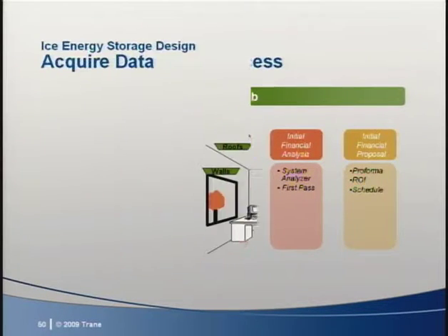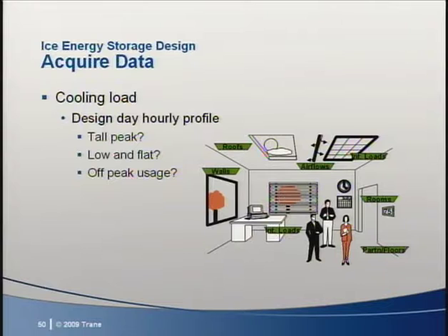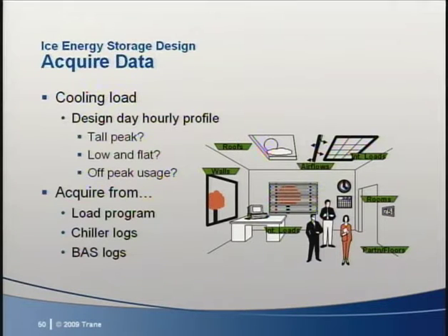It's important to understand not only the peak load value, but the shape of the facility load curve as well. Load curves for new buildings will obviously have to be acquired from a load analysis program. While existing buildings can be modeled that way as well, if chiller or BAS system logs are available, they can serve as good load information sources also.